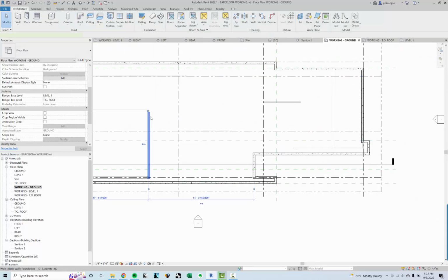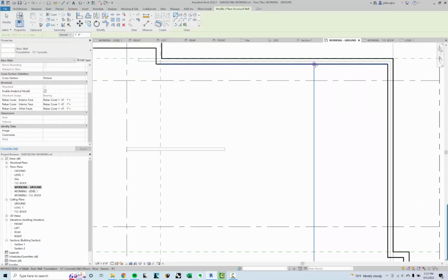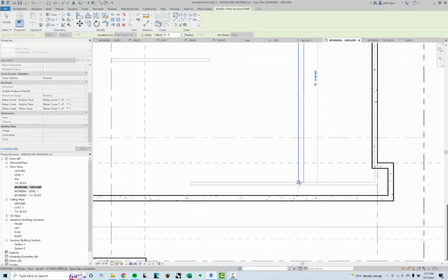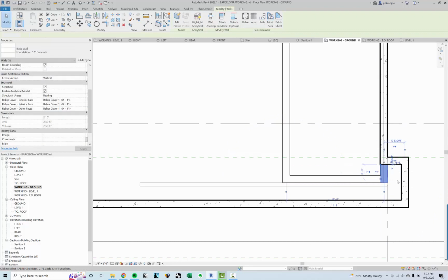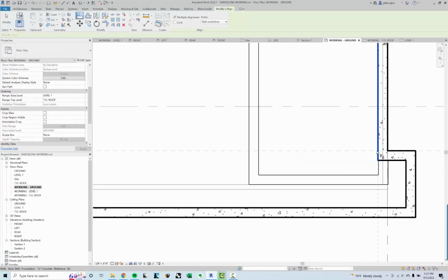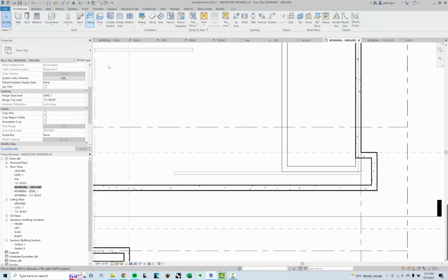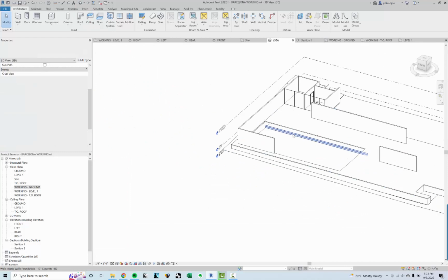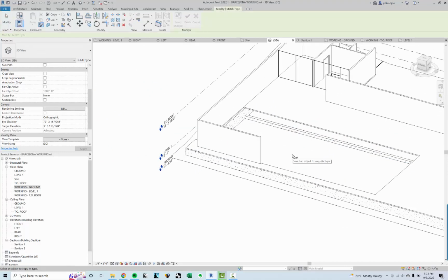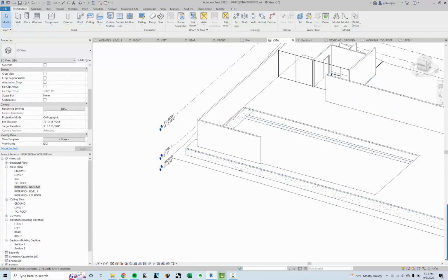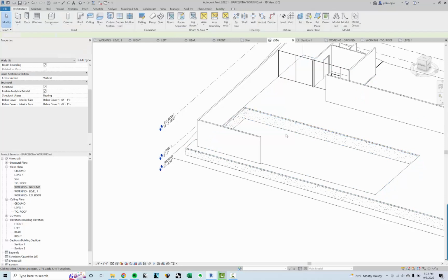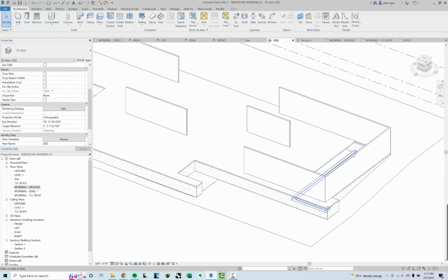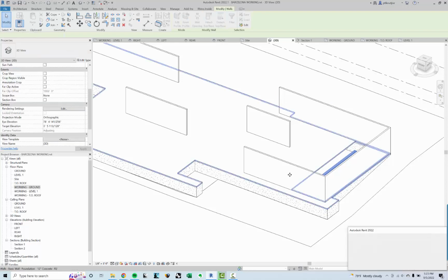Let's do the same thing over here. This one we'll just do right across. Looks like it actually goes like this. Now, these heights are obviously not right. Let me see if this works. Sometimes you can do MA, match. It only matches the type. It doesn't match the height. So I'm going to click all these and attach the top of this to there. And then I will click this and attach the top to there.